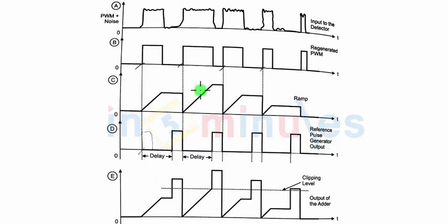And once we get these two waveforms, we are going to add them using an adder. So the output of the adder will look something like this. Wherever that constant part in the ramp pedestal waveform occurs, that constant part will be added with this constant amplitude pulse, and hence you will see a sudden rise in the final output of the constant part. So this is the output of the adder that we get. Please note that it is the result of addition of these two signals.